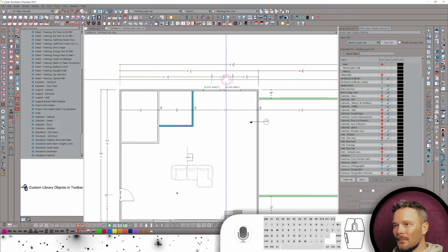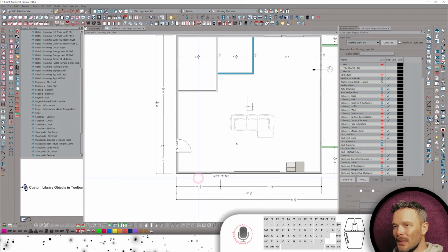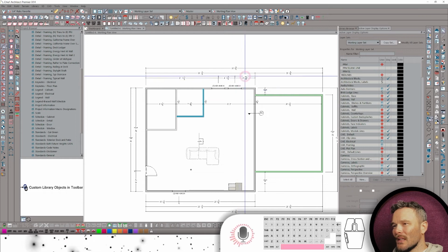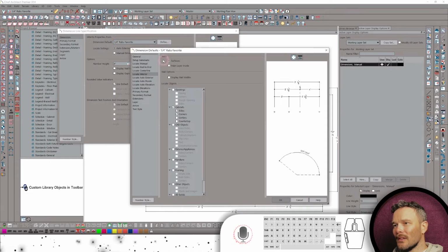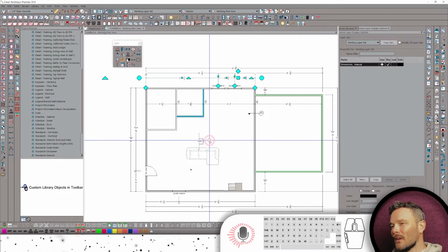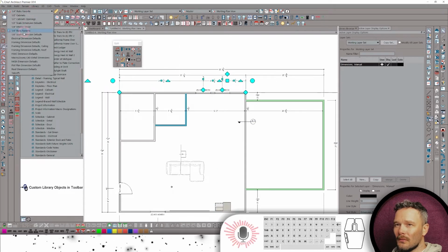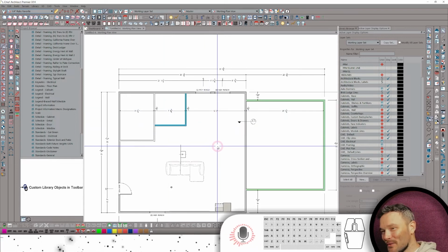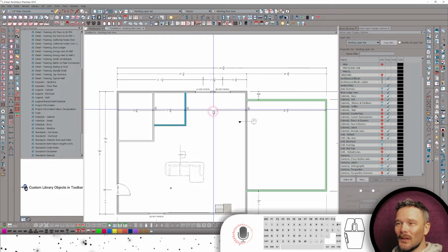And again, if we punch that exterior dimensioning, it's going to be dimensioning to center line of all fenestration. It's very easy to double click on these and then go into define, and you can change any number of parameters. But this is my favorite setup so far. I really like the ease of use. So for 1/4 inch, Rab's favorite, believe it or not, yep, it is my favorite. I use it for 90% of the dimensioning I need to do. It does work really, really well.